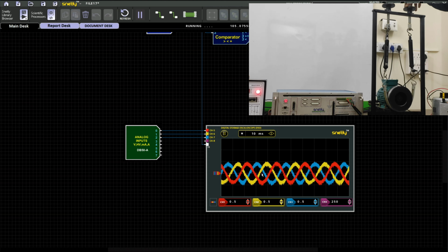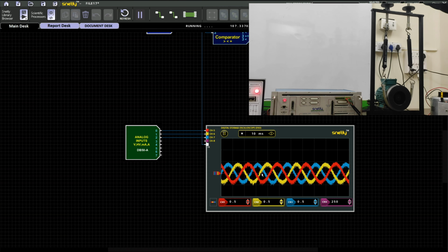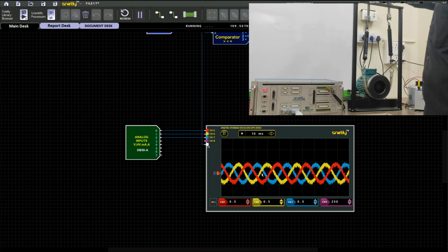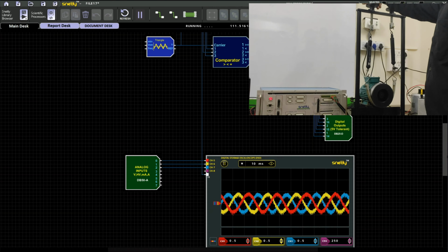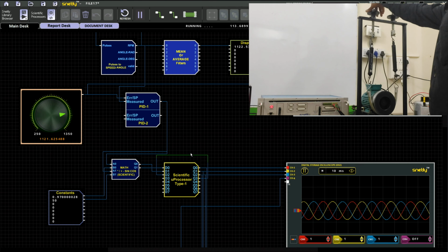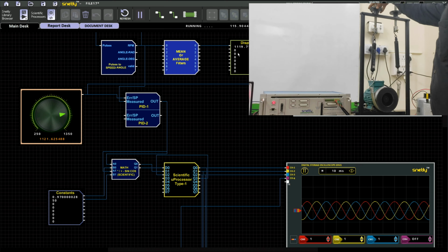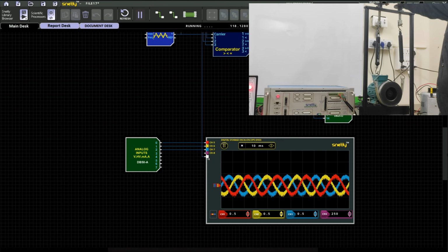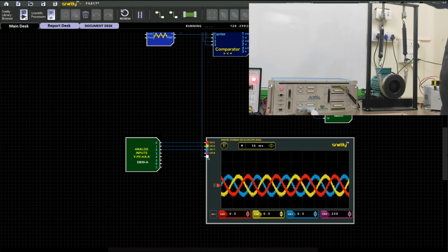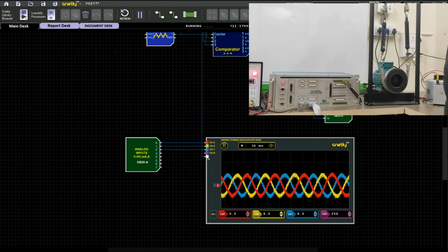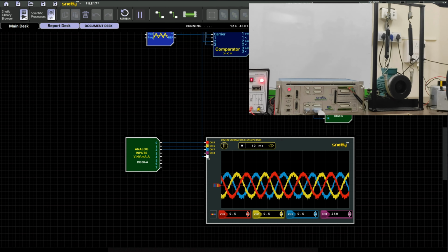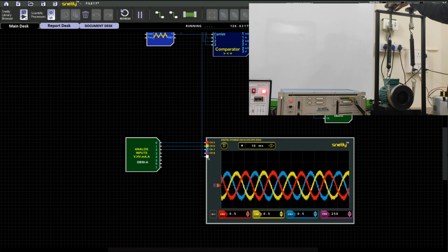Similarly for other motors, the rated ampere will be different, so we need to apply up to the maximum rated ampere. In open loop we have seen that the speed gradually decreased once we applied the load, but in closed loop, up to the motor rated ampere, our set speed and actual speed should match.